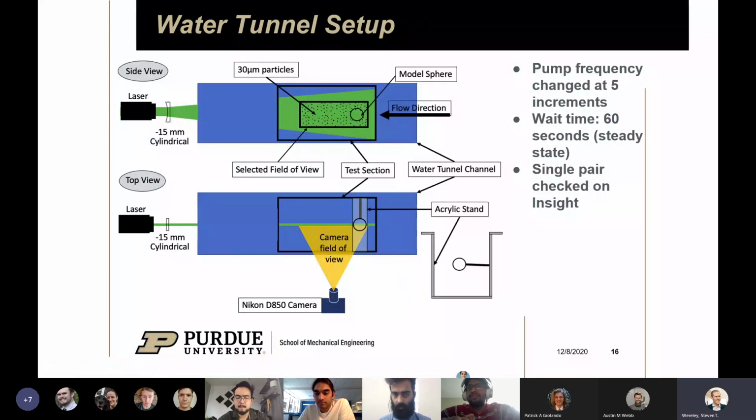But what was the consequence of that on particle size? The particle size did become smaller. In a PIV system, we want the particles to be at least 3 to 5 pixels large. However, our particles were somewhere around 1 pixel.